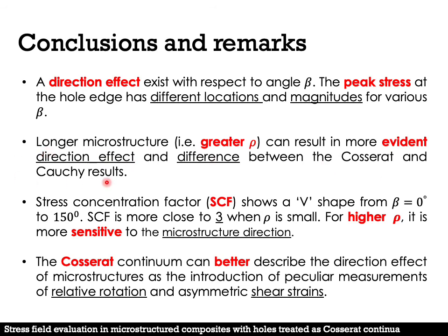The stress concentration factor SCF shows a V-shape from beta equals 0 to 115 degrees. SCF is closer to 3 when rho is small. For high rho, it is more sensitive to the microstructure's direction.